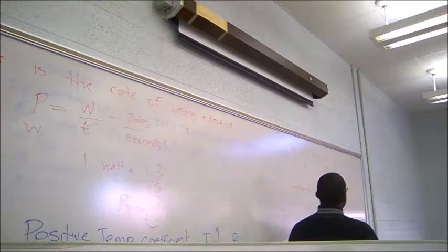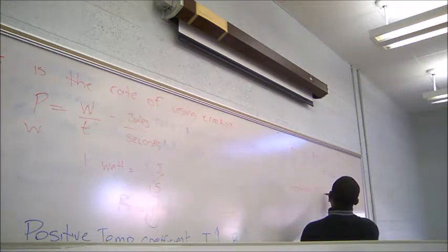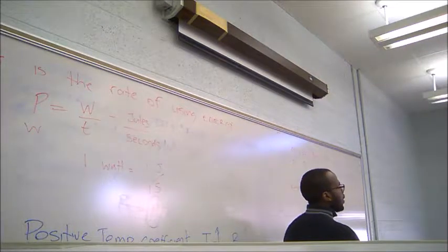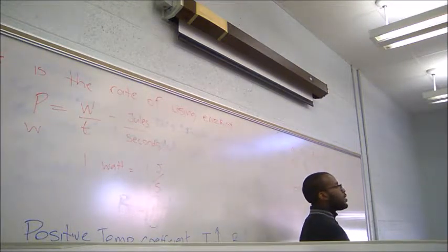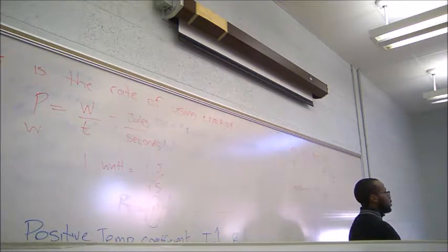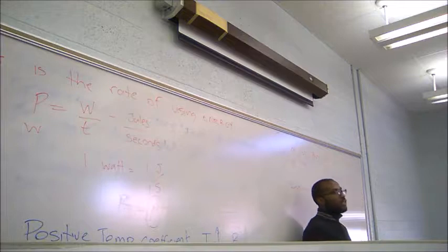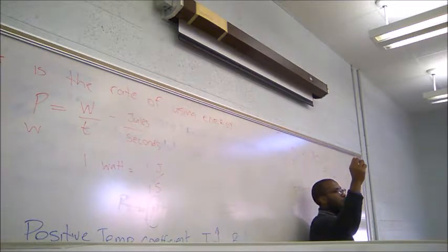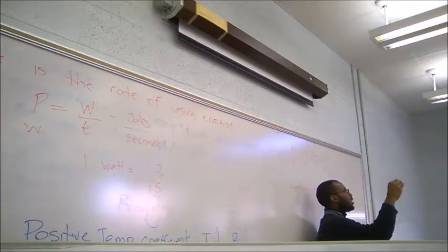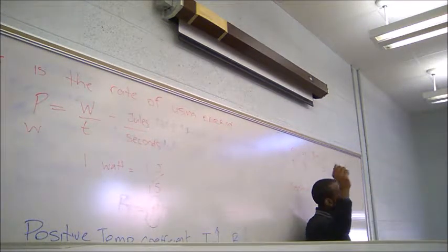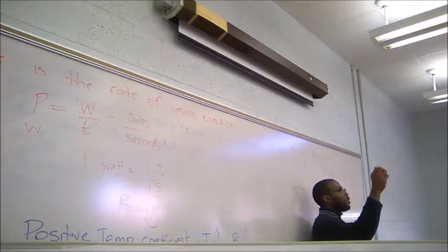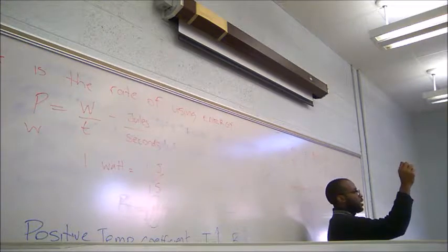And then the last one tells us, so right now we have 330 ohms, and we are told that the tolerance of this component is 5%, plus or minus 5%. And again, tolerance, the manufacturer is telling you how accurate the manufacturing process is. They're saying, hey, this resistor is 330 ohms, but based on our processes, if you measure the resistance, it can be 5% greater than 330, or it can be 5% less than 330. So what range can this be in?